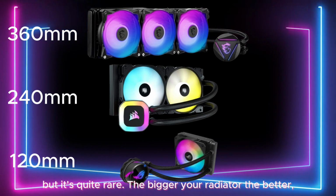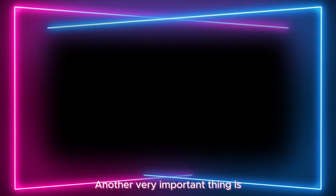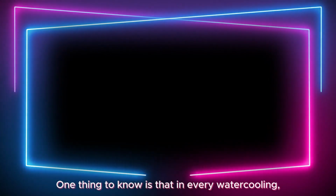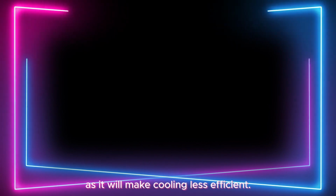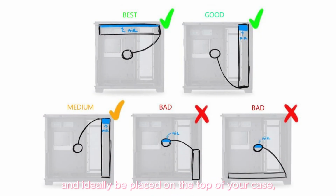The bigger your radiator, the better, but some PC cases may be too small. Another very important thing is where you place your radiator. One thing to know is that in every water cooling there will be some air bubbles. You do not want those air bubbles to be in the pump, as it will make cooling less efficient. That's why your radiator should always be higher than your pump and ideally be placed on the top of your case or on the front with the pipes at the bottom. Here's a diagram about where to put your radiator.